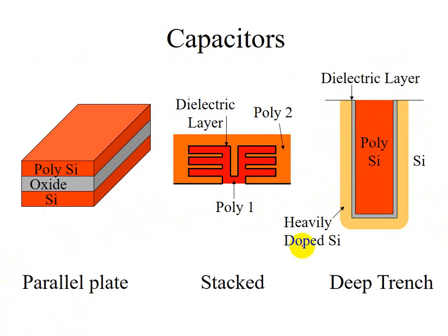And then this will be single crystal silicon, so it's a heavily doped single crystal silicon, and this is the dielectric layer, the insulating layer, and then again you deposit polycrystalline silicon here.